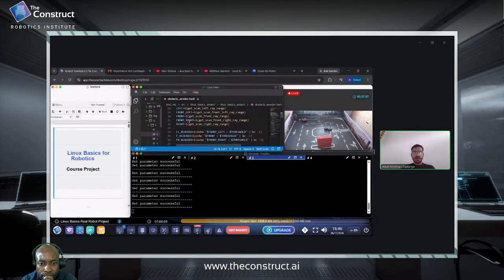And out of all these sensor values, we are using three conditions. The first condition is front left being blocked and front being blocked, or front right being blocked. For that, what we are going to check is if front left that we are getting from the rover is less than the threshold, and we have given a bc minus 1. This basically means that we need an integer value and not any decimal value.